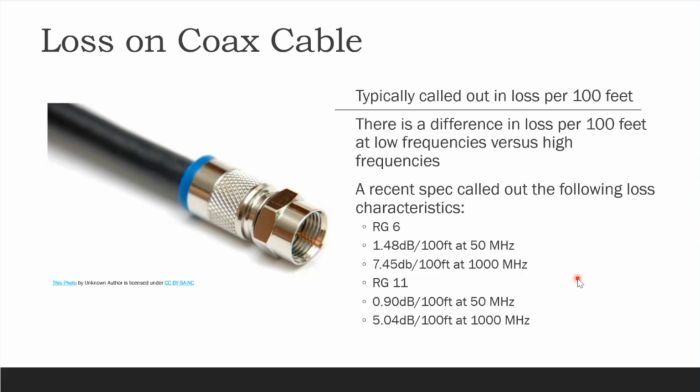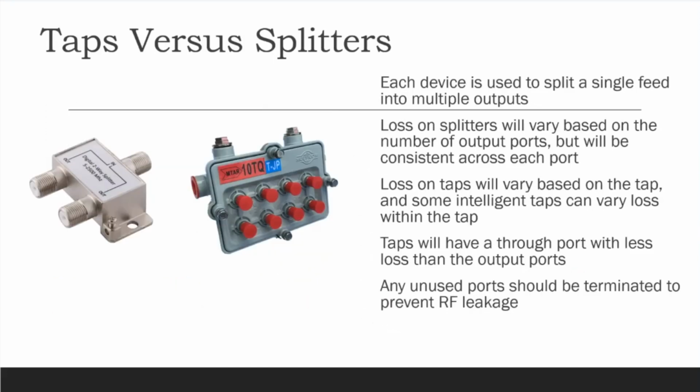So you get loss in so many different places, right? You have this beautiful signal coming in, it's clean, it's at the right power, and then as soon as you split it, as soon as you put it on a cable, everything gets worse. It gets less powerful, and then you potentially have to amplify, and you have all kinds of issues there. You could potentially be amplifying noise into your system, if you over amplify, or if there's already a bunch of noise in the system. I'll touch on over amplification on the next slide.